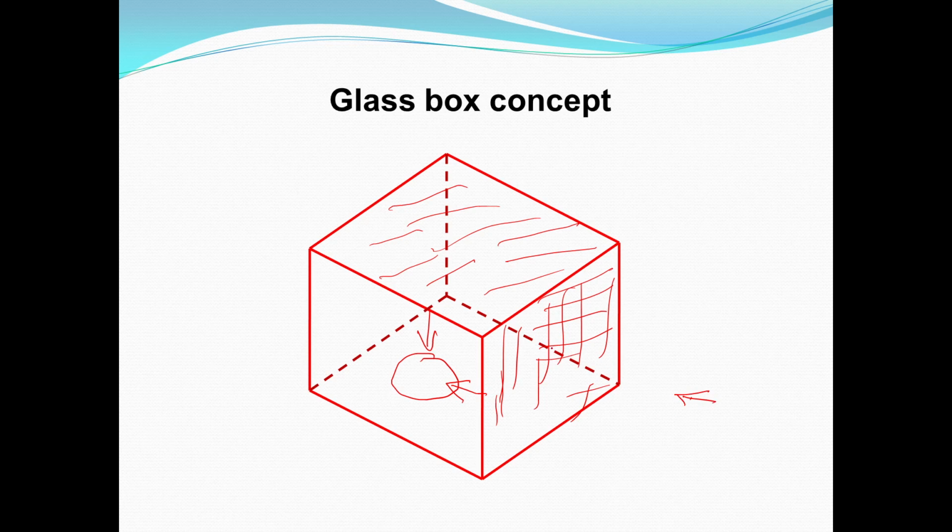Observer, plane, object. So you get the projection of the front view below the xy line, and here the projection of the object for the top view on the horizontal plane after rotation, that is clockwise rotation of the horizontal plane. We get the views of the object in the third quadrant: the top view above the xy line and the front view below the xy line. This is the xy line, the intersection of the two planes.